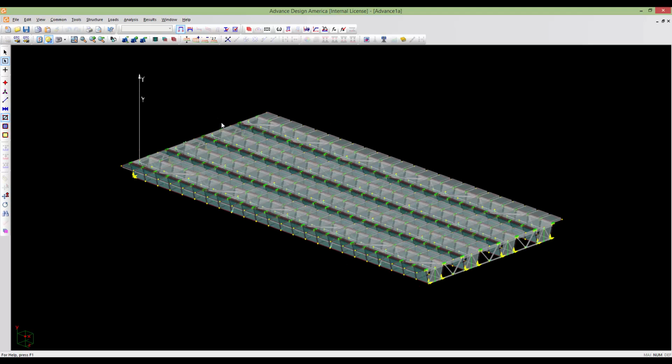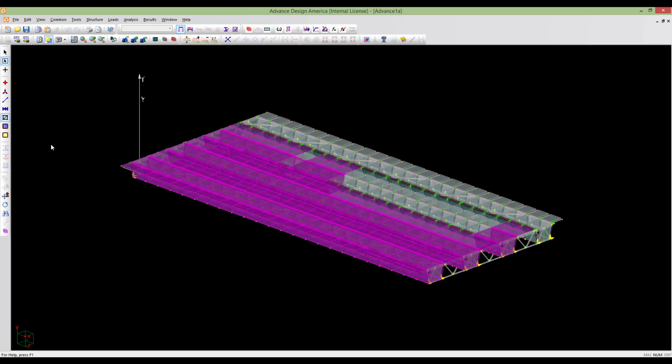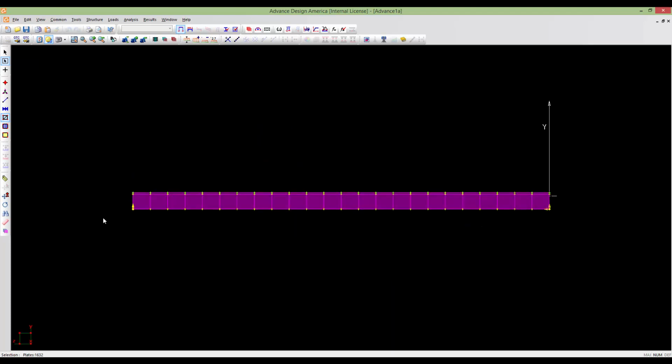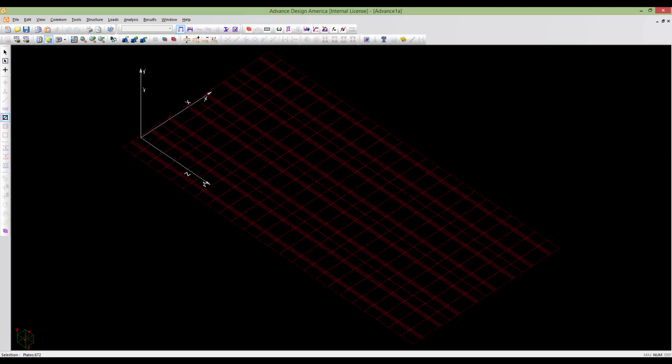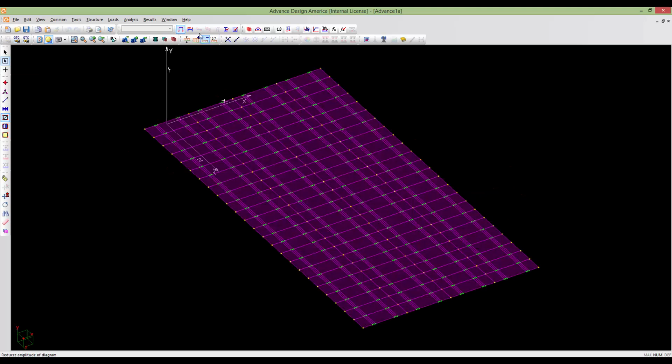And right now I'm going to apply these load cases manually. So first one will be the cast concrete. So select the mesh, side view, select just the concrete finite element plates, mask them. Okay, and now we can apply the cast concrete here manually.